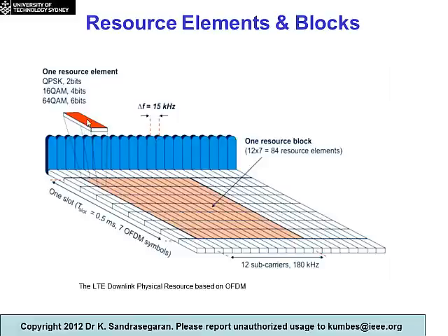The number of bits that are essentially put into a resource element depends on the type of modulation scheme we use. For example, if you use QPSK, we are transmitting 2 bits within that resource element. If we are using 64 QAM, we'll be transmitting 6 bits inside this resource element. Again, that depends on the modulation scheme that is being used. But essentially, it's one OFDMA symbol.